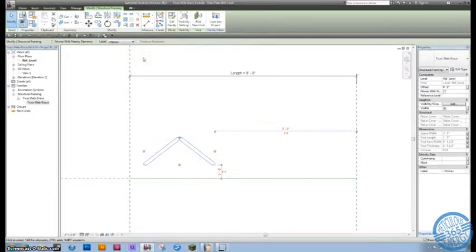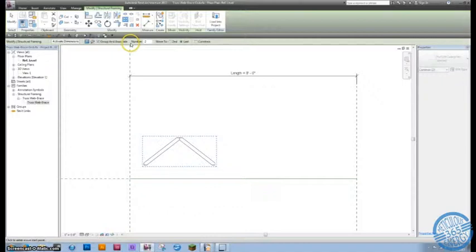And then we can just jump right into the array tool, because all of the controls on the array come after it's been built. These are your values for the array. Please note that we are in a linear array at the moment because we are doing a linear line-based family. You can do these arrays in a radial fashion. It works in the same method, but this is linear.